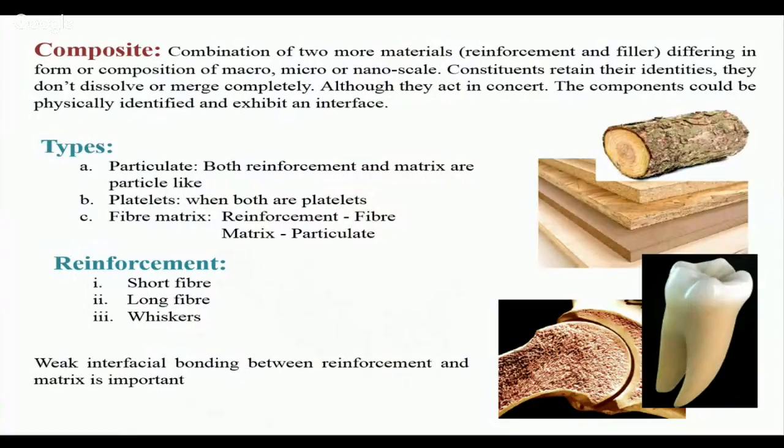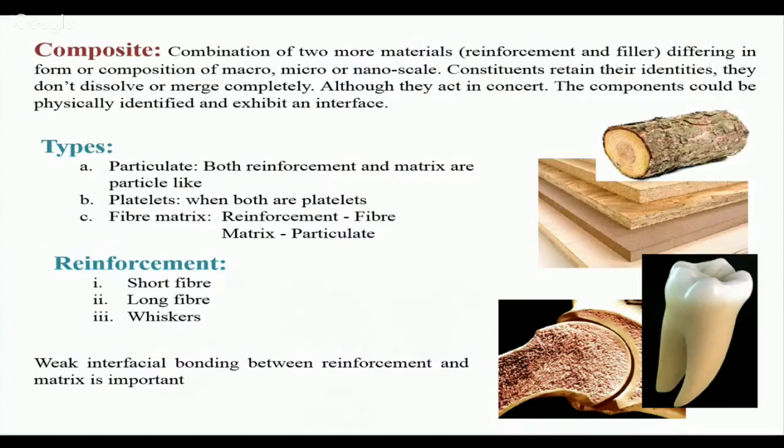Similarly, in case of particulate, we'll see later on. I think somebody was asking about composites, zirconia dental implants. There we'll see that zirconia is a toughening agent, and zirconia is also a matrix. Here we will see zirconia tetragonal phase and zirconia cubic phase both working in concert, where the cubic phase is the matrix and the tetragonal or monoclinic phase will be like a toughening agent. I think we will discuss later on in the next session. But as I said, in the particulate composite, the reinforcement is a particulate as well as the matrix is particulate.